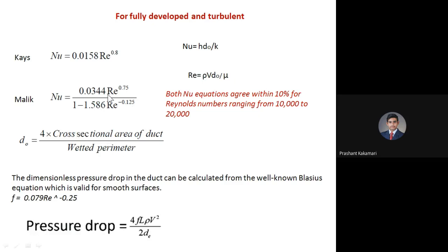So how is Re calculated? I think everyone knows how to calculate the Reynolds number; we have studied from third semester to this semester how to calculate it for any given flow, that is rho V d by mu. Or here one can consider rho V times the characteristic length or the effective or hydraulic diameter for pipes, that is rho V D naught by mu.